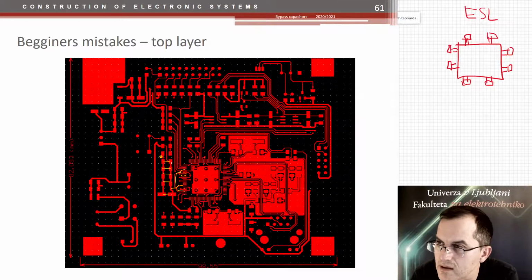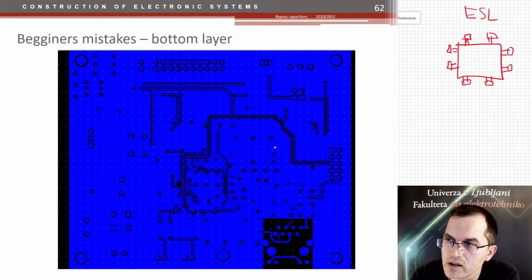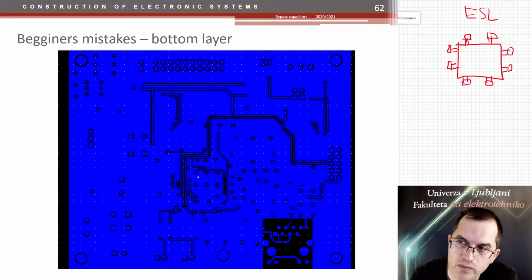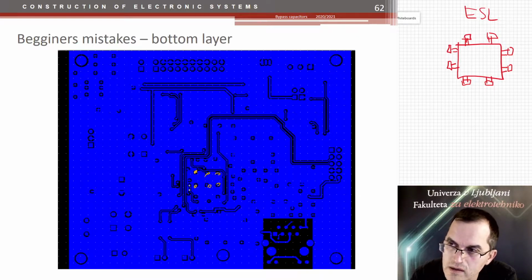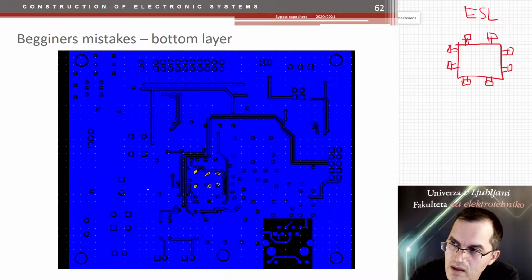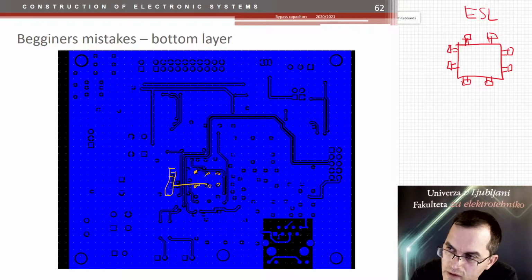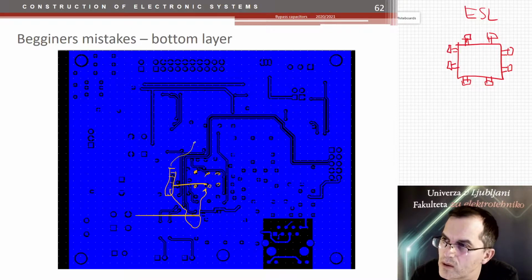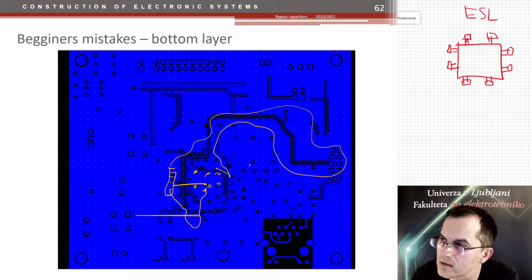I'm not sure, but nevertheless, if it's on one side or another, if you check on the bottom, there are a lot of tracks that are breaking the ground plane below, and these are the wires here that connect to the ground of that controller. And here these are the capacitors. And now the ground is broken. You have to go around here, back here, or maybe all around there. I don't know how far away to come. No, here.